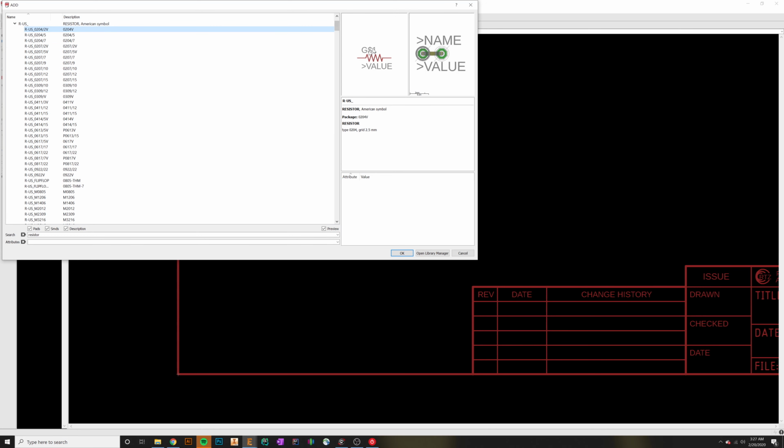And you see that all that is actually varying, because if I go through this, you'll see that the symbol actually stays the same. But on this side, this is actually showing what the physical board layout will look like for the component. So if I move through here, this is just a direct jumper short using a wire. This is a smaller resistor with some small leads on it. And as I increase it, you can see that it's just constantly changing. It's kind of hard to say which one I would need, but I think the standard size is going to be your 12.5 millimeters.